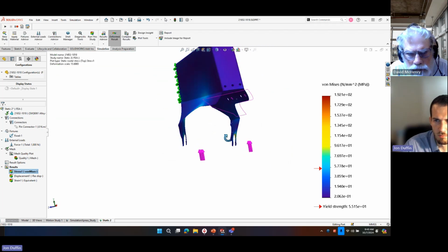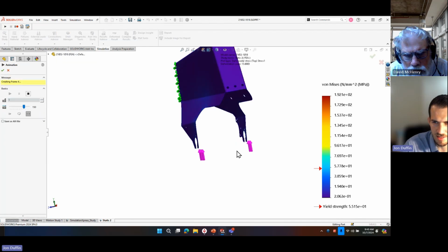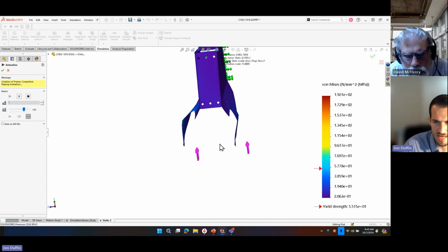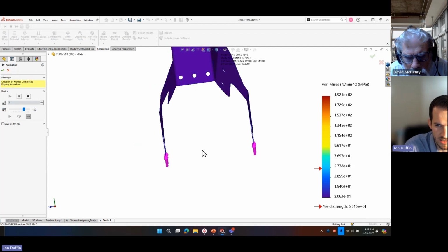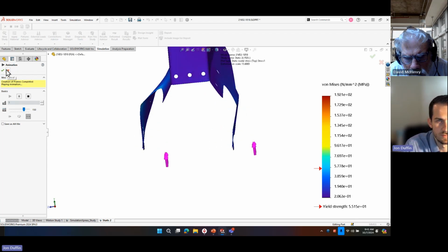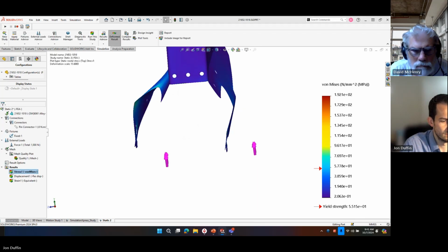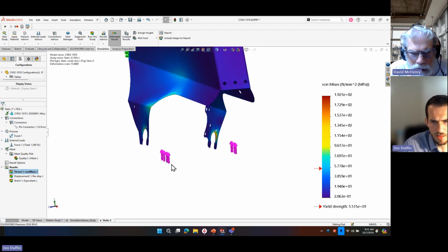Now I see both of them moved in one direction, but they all stayed the same. So now I animate this, and you see those two are now staying together, but it's just bending off to the one side in this case. We can see that pin is keeping them at a relative distance, stopping them from translating, like you would with an axle, or I guess represented by an axle on that front. That's interesting, but it's because the surfaces that you picked are not symmetrical. They're not equal on each side.